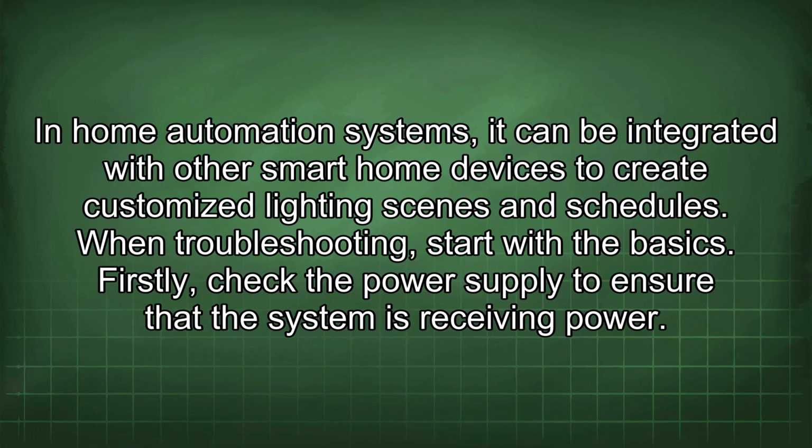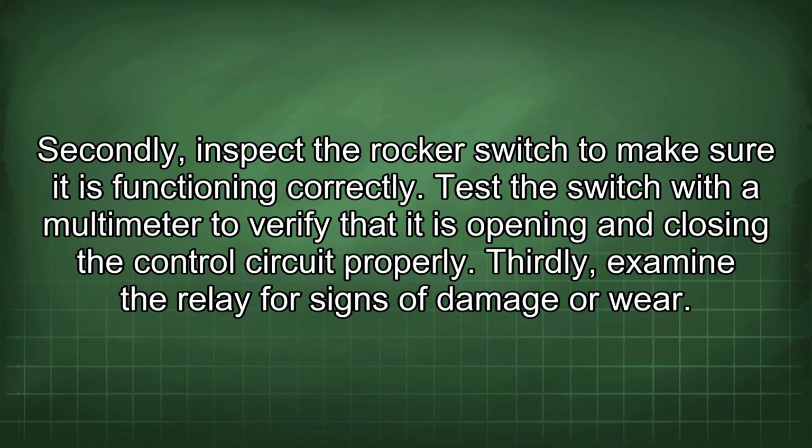When troubleshooting, start with the basics. Firstly, check the power supply to ensure that the system is receiving power. Secondly, inspect the rocker switch to make sure it is functioning correctly. Test the switch with a multimeter to verify that it is opening and closing the control circuit properly.